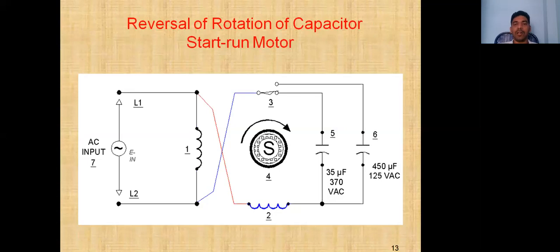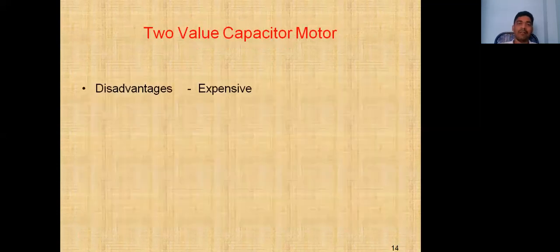Reversal of rotation of capacitor start capacitor run motor. Here we reverse the main or auxiliary winding connections.